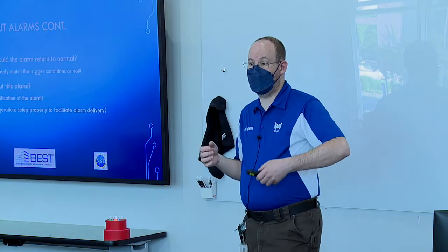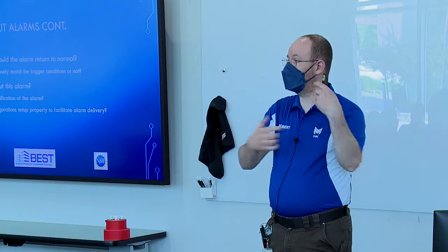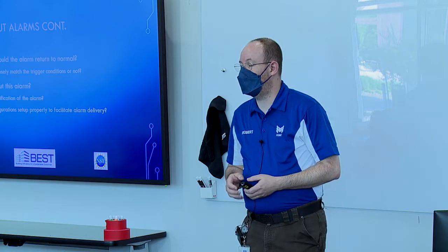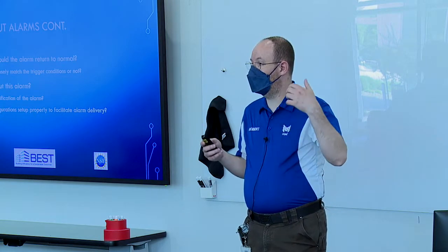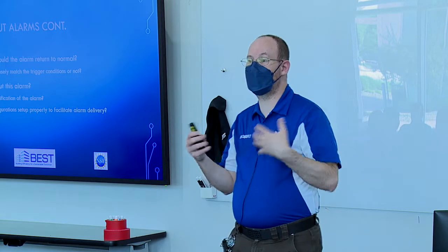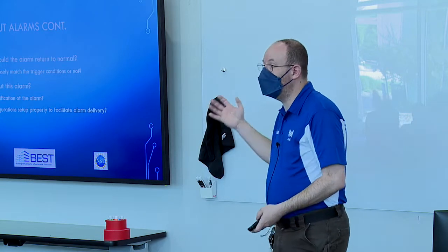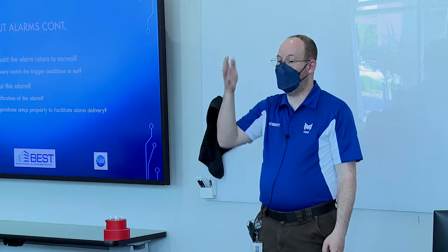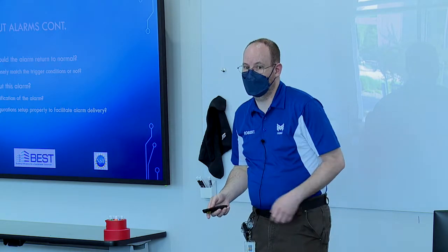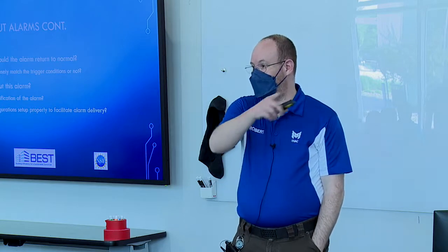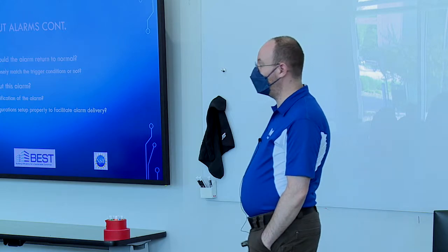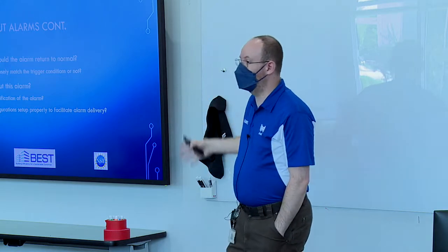Are we sending it to a central workstation that everybody checks every half hour to get their to-do list of what they've got to go fix? Are we texting alarms to the on-duty phone? Those types of things. Is the email client properly set up on our supervisor so that it actually sends the alarms? Brad laughs because he's lived that one. But there's a lot that goes into alarms.